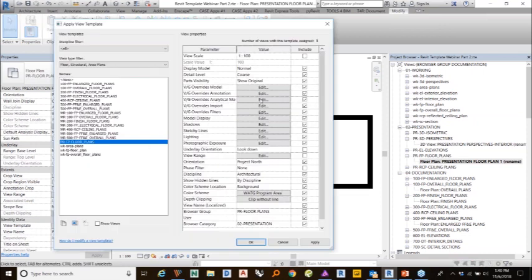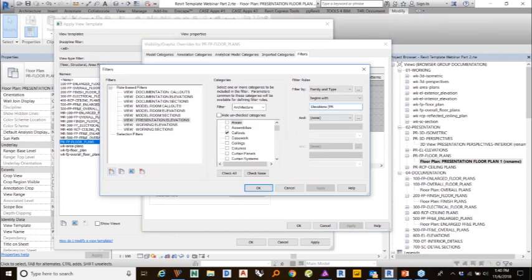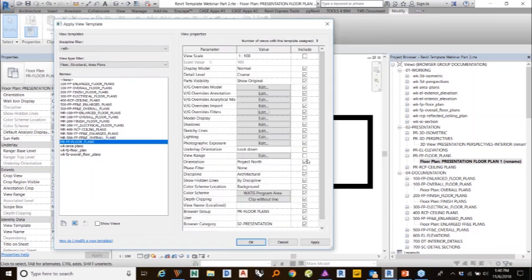And how you do that is you have global control through your filters, where inside of this presentation elevation view filter, if we go even further in, first off, I've overridden the patterns of it, and second off, I've applied it to multiple views. So what it's doing is it's filtering all families that have the name PR in their elevation. So because my families that set up that elevation view are called PR, it's going to know to turn it red and to highlight it for you.